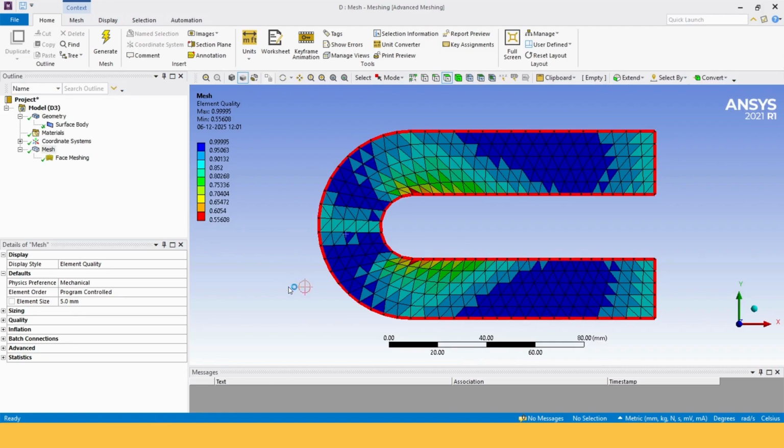Why does the tri-mesh perform better here? Because triangles are naturally flexible. They can rotate, shrink, and fit smoothly into tight curves without forcing the mesh into unnatural alignment. In regions with bends, organic shapes, or irregular boundaries, triangles provide higher minimum quality and smoother transitions.